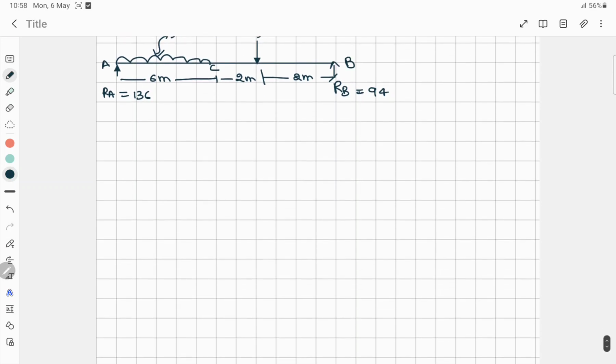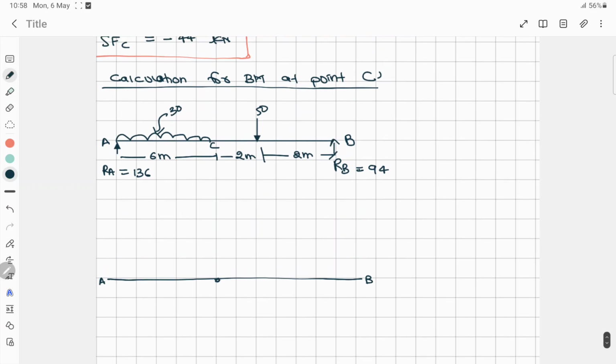Now the bending moment diagram for this one will be like this, and we are finding for C, so the maximum value will be at C. I have explained this in my previous lecture, so go through it once, so that you will be clear about how to draw the bending moment, shear force, and the IL for RA as well as for RB. Now at this peak point, what will be the formula? L minus A divided by L into A. So let's find for this one.